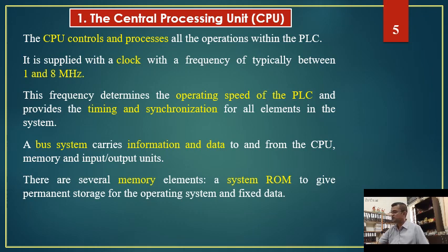And one more thing is, we often call it POST, power on self-test. That POST operation always remains constant. Every time whenever we switch on a CPU or PLC, that set of jobs needs to be mandatorily done, which may include the testing of input devices, testing of output devices, testing of memory devices, then loading the operating system, and so forth.